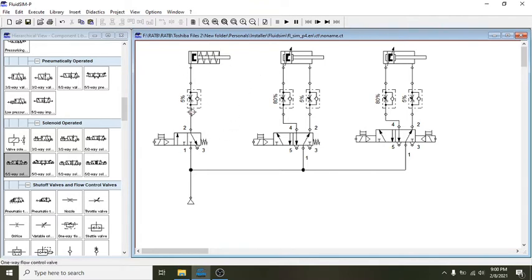Okay, so you can just alter one speed only, for the single acting cylinder. But then the functionality as to when the cylinder can extend and when the cylinder can retract is the same as with the double acting cylinder using a 5-way single solenoid valve.